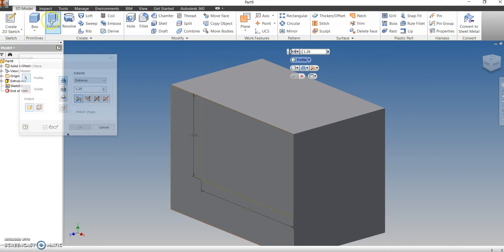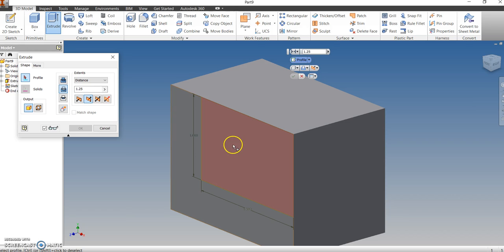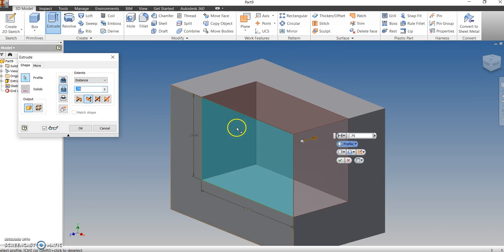And we're going to extrude that. We're going to cut through. And we want to make sure we're cutting through this section here at a specific distance. And that distance is going to be 0.75. So we're not cutting all the way through, just through a certain segment of it. So you can see here's that segment. All right, 0.75. It's 3 blocks. Remember, each block is 1/4 of an inch when you're referring to your drawings. And again, we're just going to go 0.75 back and click OK.